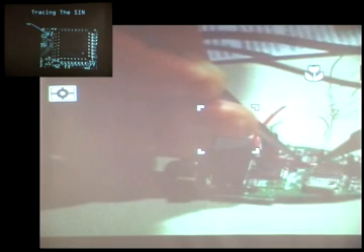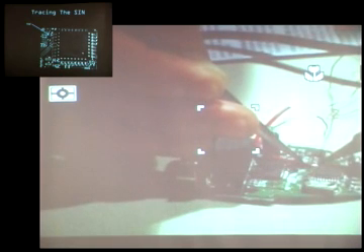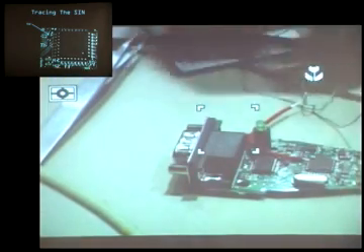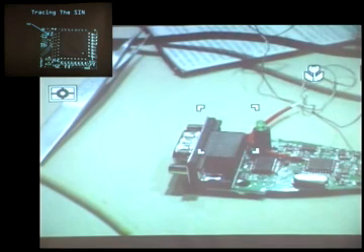And let me see if I can do this without blocking the light and still getting my head close enough to see what I'm doing. Alright, so take the tweezers, hold up to the side, apply a little heat to the workpiece, and I see the phase change happen, and I've got one wire attached, good and solid. Hooray. So I'll try the other wire really quick. One more wire.